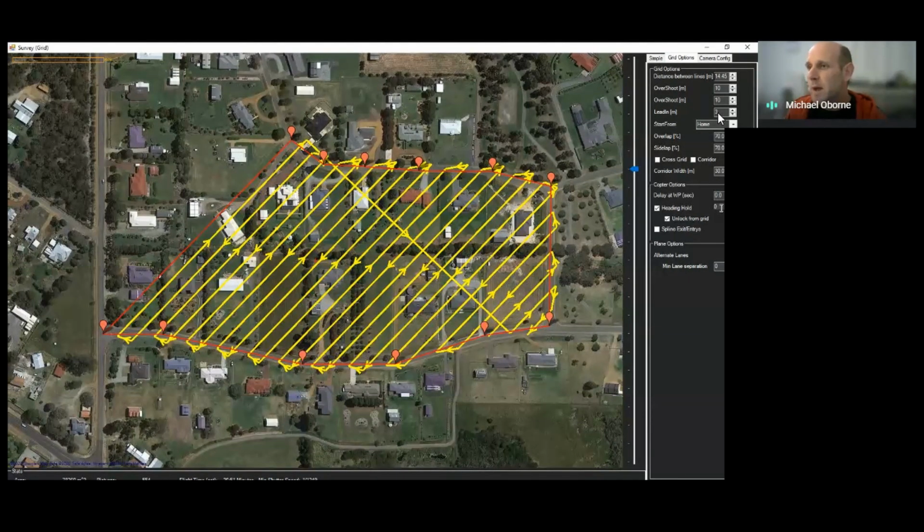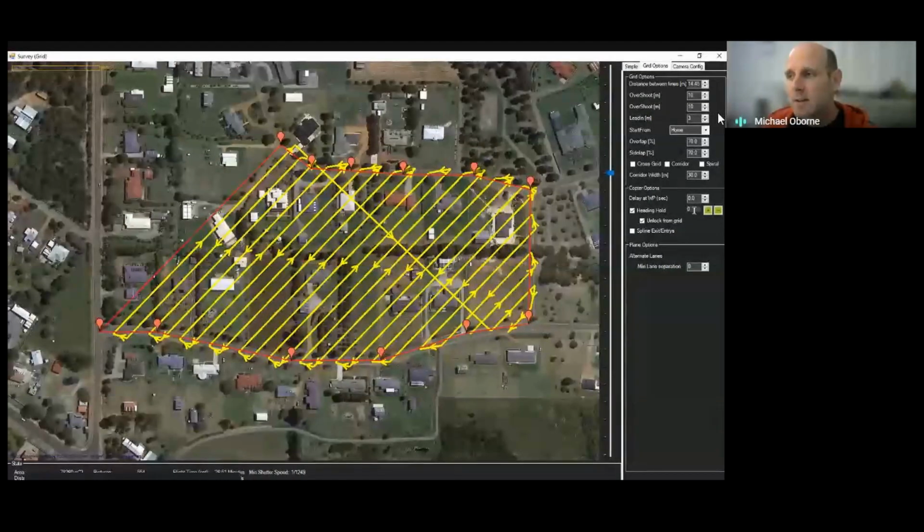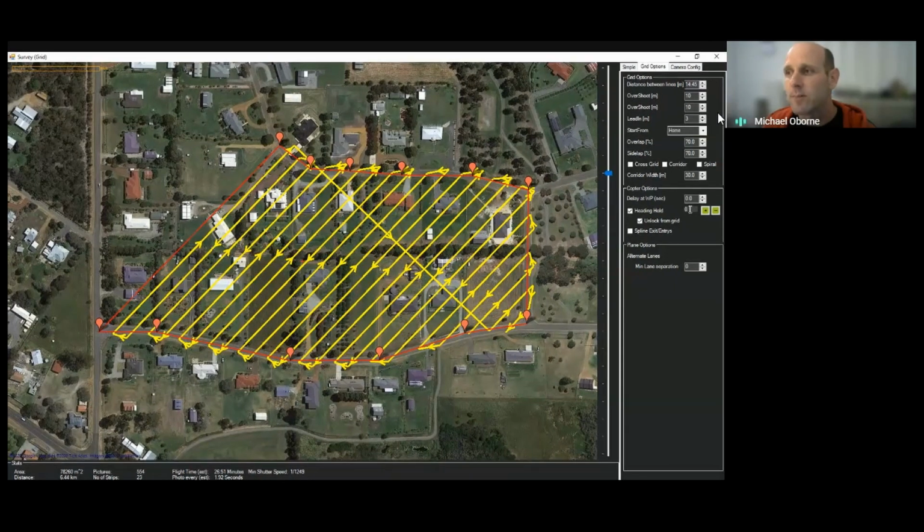So it's one way of making sure that the camera is facing a specific way, if you had a requirement for that, or if you were flying a different type of sensor, say a magnetic sensor of some description, and it needed to be always pointing north. You can make the copter fly any direction you want and keep the copter itself always pointing north, but it'll just lean a different way to move in that direction. So I'll just turn that off for a second.